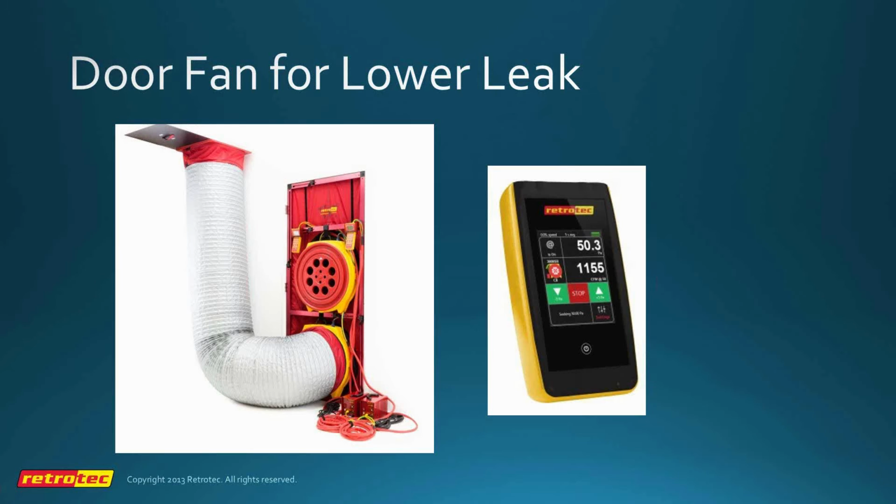It was a two-man job, you'd have one person waving their arms and another person adjusting the knobs. It was very confusing. With this system, all we do is set the room to the pressure we want. We set the flex duct fan to zero, so we have a hose above the ceiling and one in the room, and we just let it balance itself out, which takes a few minutes, and then we take our readings. Works like a charm, actually, and in our new online training, we have Denelli doing this particular test in his office.